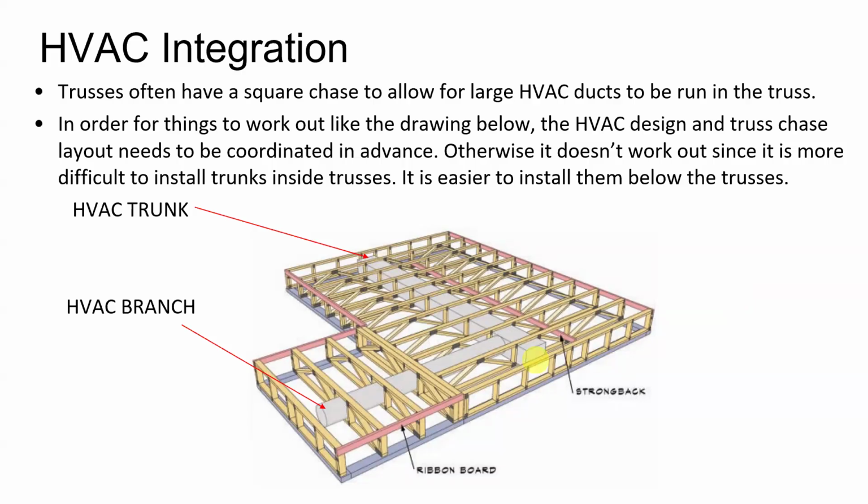it's harder to install your duct in this trunk, especially if you're trying to insulate it and do the connections. So, if you've got it all set up and you can push it in from the end, and in my experience, unless you've got the HVAC people online from day one when you're designing the house and they agree and say, hey, based on this layout you're showing us with the floor trusses, we can get our HVAC ducts up in the trusses. But if you just leave it up to them, it's a lot easier for them to run it underneath.